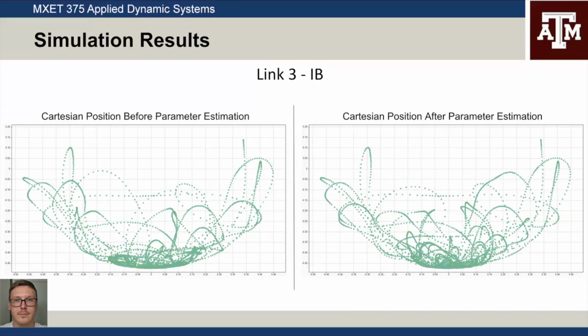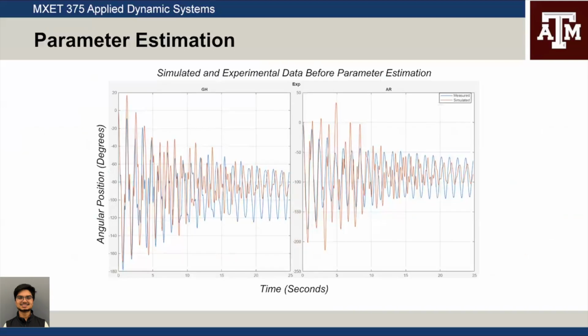These changes show that even a seemingly small change to damping can have large consequences to the rest of the system. So for parameter estimation, which is what we did, is to fine tune the frictional coefficients of the bearings. We modeled it as damping.